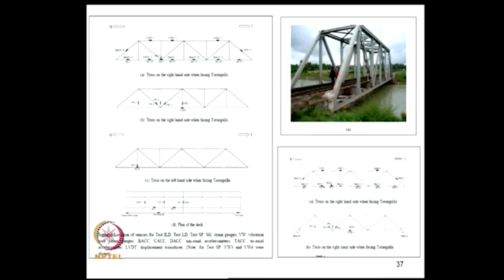So the best way is to apply the loads that are permitted on these bridges and then take measurements of the kind that I mentioned, and make a finite element model whose predictions are reconciled with the measurements made by updating the model parameters or details of modeling. And then on the updated finite element model we can apply enhanced loads, make the loads move with faster speeds, and so on, and predict the performance of the structure.